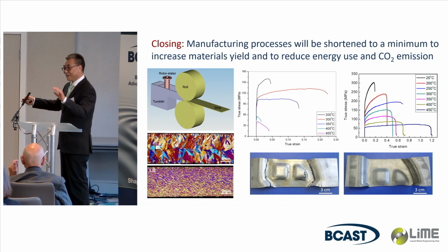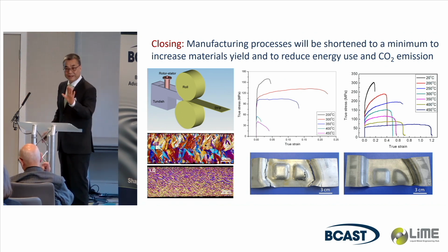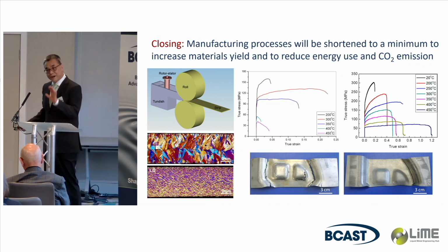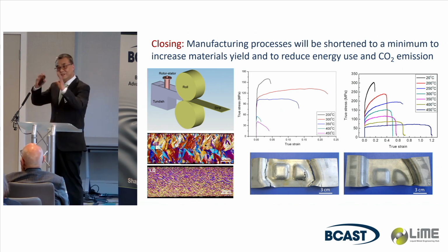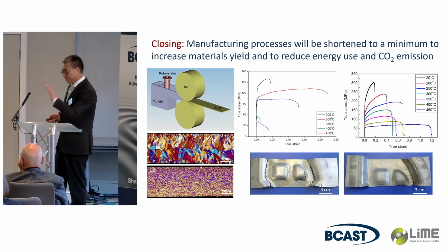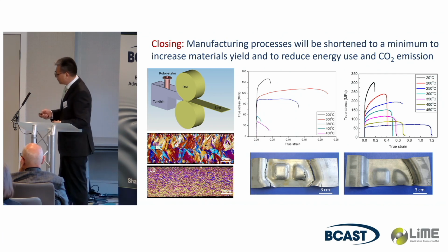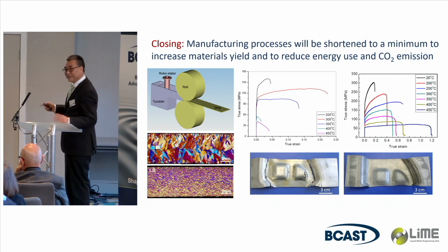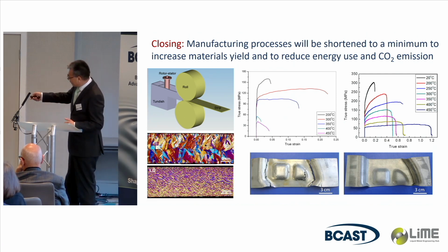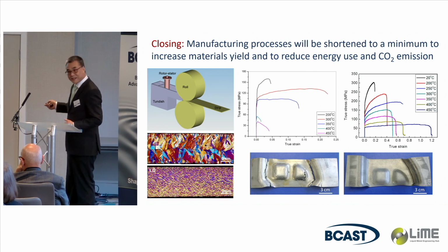Because of fast cooling, you get very quick dendritic growth and push the solute metal, becoming centerline segregation. That's one problem. By high shear, by enhancing the nucleation process, what do you get there? There's no dendritic solidification. You don't have this process pushing solute metal, so we successfully resolve the problem of centerline segregation and refine the microstructure by 2 orders of magnitude compared with this. The consequence is you can cast thin strip and direct stamp without hot rolling.